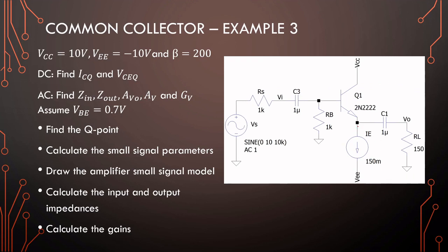and I'm going to show you why. We don't necessarily know what is sitting at this node exactly in terms of DC voltages, but we can apply Kirchhoff's law to the closest ground. We know we want VCE, we have VCC, we have VBE, we can figure out what our base current is, and we know our RB value.